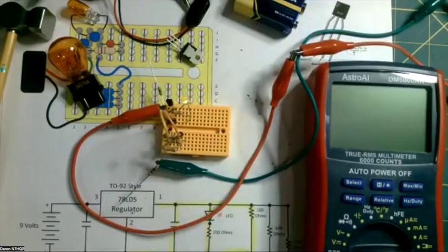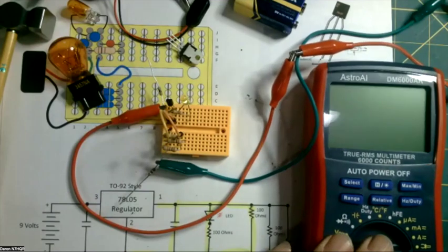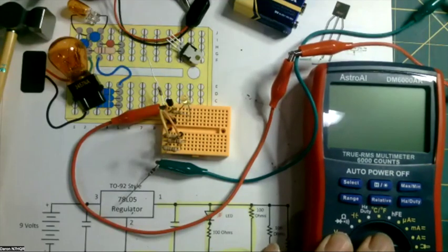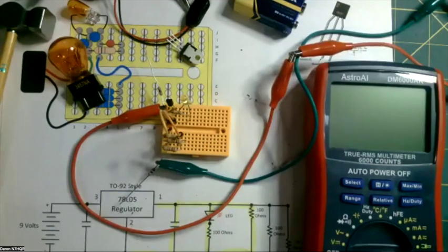Okay, well, now what you need to do is put enough load on it to cook the 78L05. Yeah, you need current now. You know, just for information, the spec sheet on the 78L05 is 100 milliamp. And we're drawing? Ours are, pardon? We're drawing 60. 60 milliamp right now? Okay.